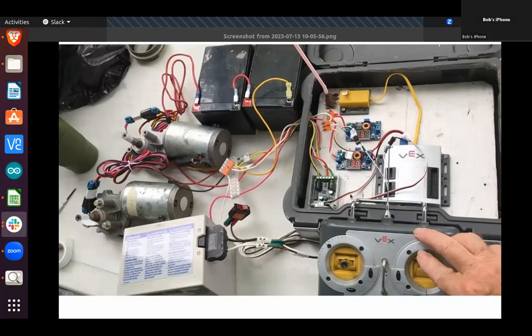And then the 12-volt battery, the one down in the lower left, that controls the electronics. That comes up into a step down. You'll see a donut ring on the blue board at the bottom there. That goes from 12 volts down to 9 volts, which powers the VEX, that silver box. Also 12 volts comes into the next step down and goes from 12 down to 5, and that's for expansion.